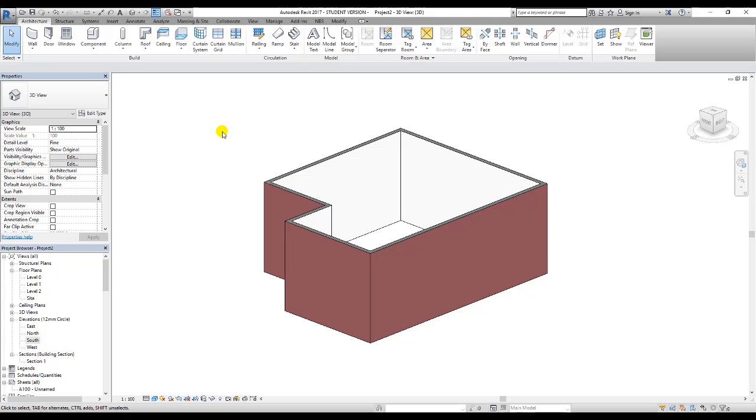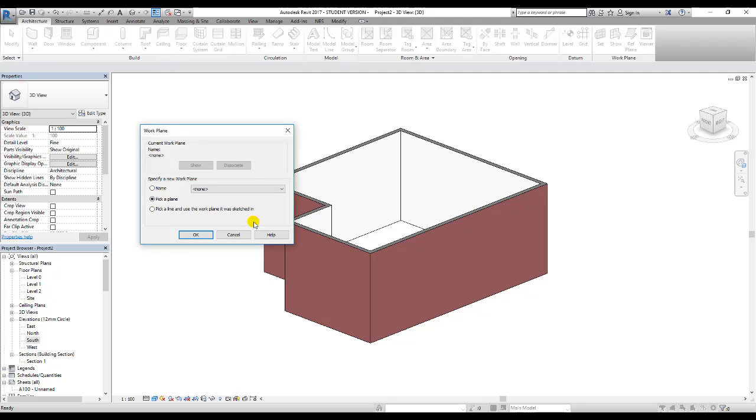So roofs by extrusion next. So drop down and then roof by extrusion. To do that, you've got to have a plane in which you can work from. So I can use the 3D view and just go to the roof by extrusion option, and say I wanted a roof that came sort of over like this, like an arch, and going this way.